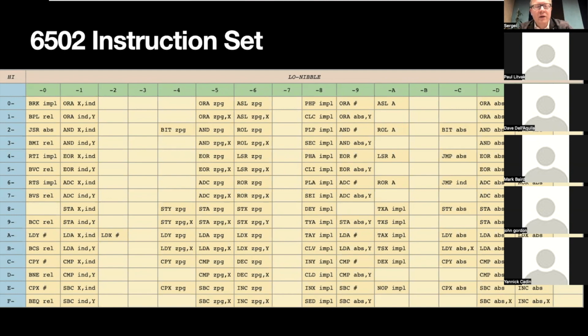There are a lot of instructions that have different opcodes, operation codes, because they have different addressing modes. We won't touch this today, but it's less. It's like 70 to 80 instructions in all, but with different types of addressing modes they make up something like 156 operation codes.